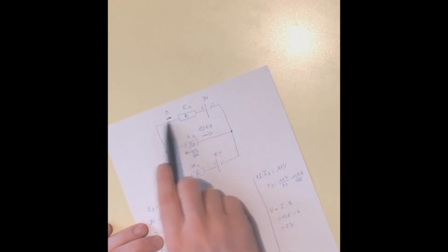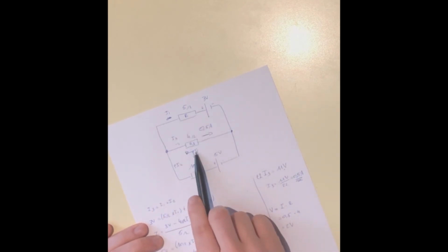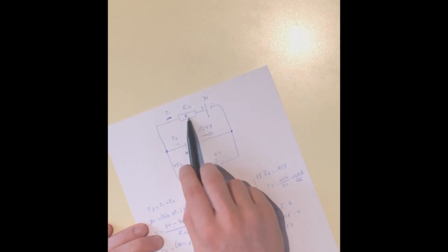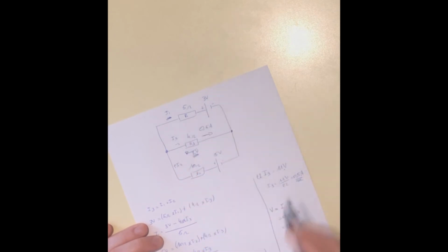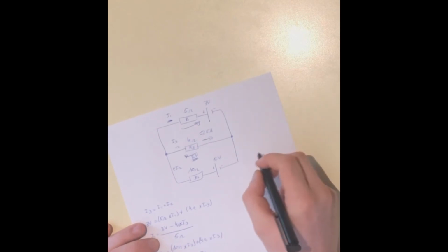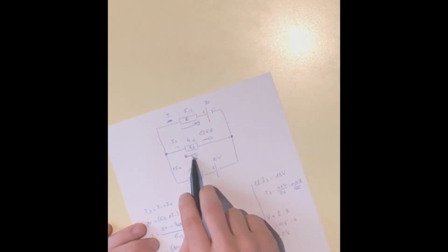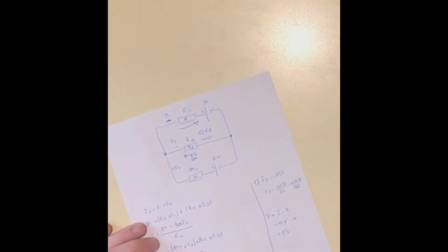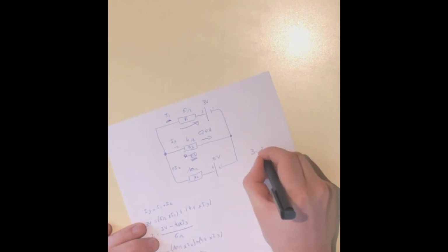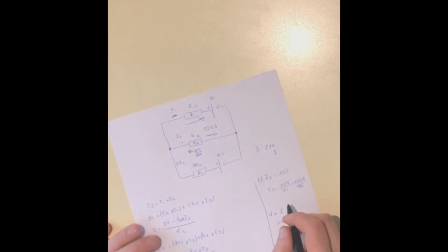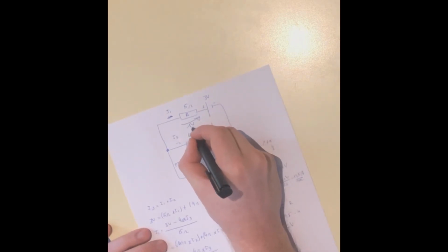Now if we look in the upper circuit, 2 volts, and we use the voltage law, 2 volts plus something we don't know is equal to 3 volts. So this voltage has to be 1 volt because we have 2 volts plus something we don't know is 3 volts. So we have the formula 3 is equal to 2 plus x. What is x? X is 1. Yeah, pretty obvious. So we know there's 1 volt over here.